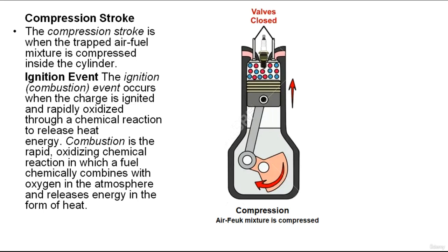The compression stroke begins as the piston starts to move from BDC. The intake valve closes, trapping the air-fuel mixture in the cylinder, and the upward movement of the piston compresses the air-fuel mixture, thus heating it up. At TDC, the piston and cylinder walls form the combustion chamber in which the fuel will be burned. The volume of the cylinder with the piston at BDC compared to the volume of the cylinder with the piston at TDC determines the compression ratio of the engine.